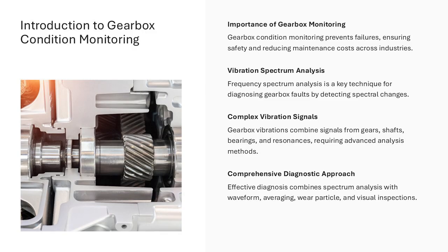This presentation focuses on diagnosing gearbox faults through analysis of the vibration spectrum, with emphasis on the gear mesh frequency, GMF, its harmonics, and associated sidebands. These spectral features provide insight into gear health, load conditions, alignment, and tooth integrity. However, it is important to recognize that spectrum analysis alone may not uniquely identify every fault type.